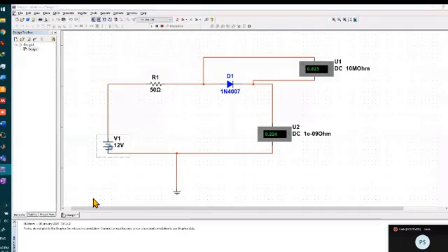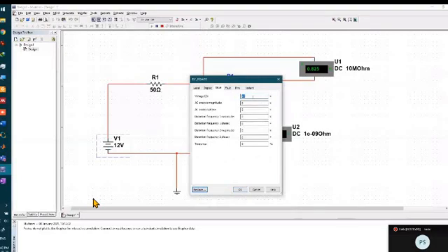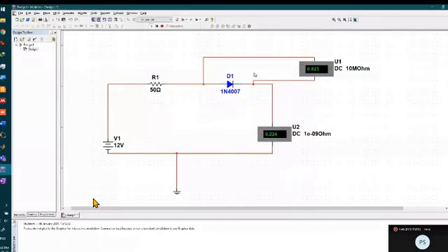If we increase this voltage, say we keep it to 25 volts and we resimulate it, let's see, current should increase. Now it has increased to 482 milliamps, that is 0.482 amps. So we want to plot the VI characteristics for forward bias as well as reverse bias.